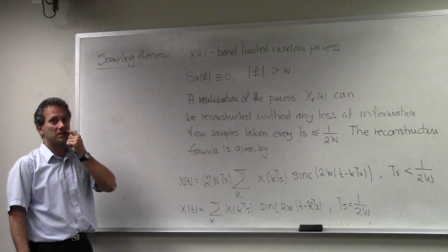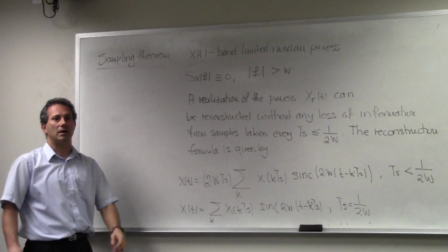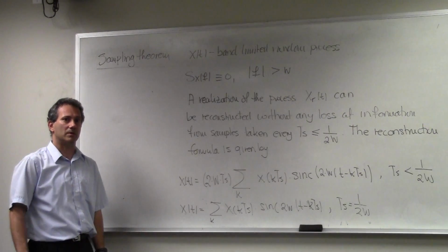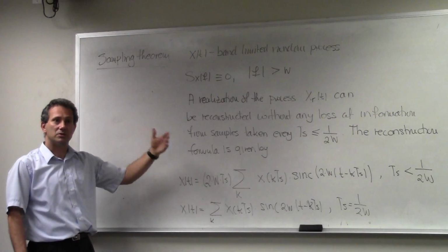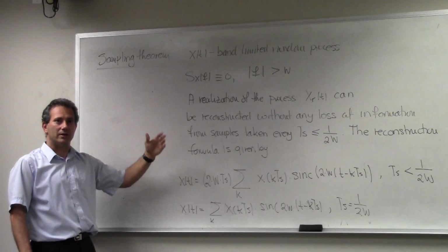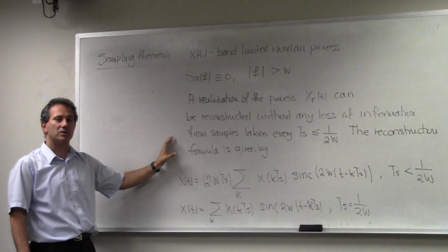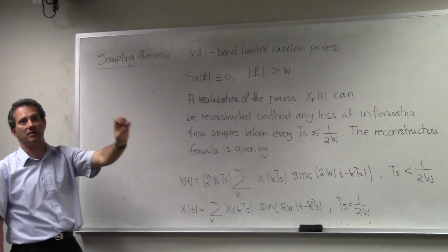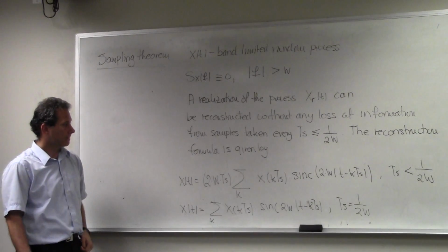But the majority of signals, where it's our interface with the world, because the world is analog and our computers are digital, we have to do sampling. And this whole analysis that we went through up to this point, determining stationarity, determining the PDF, determining the power spectral density, is all a precursor to us sampling and moving from the analog to the digital domain.